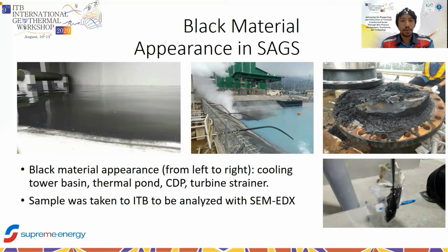So we had to shut down during the commissioning program because of the clogging at the turbine strainer, and we had to wash all of it. The fact is that it was black. And then some samples were taken to ITB to be analyzed with SEM-EDX.